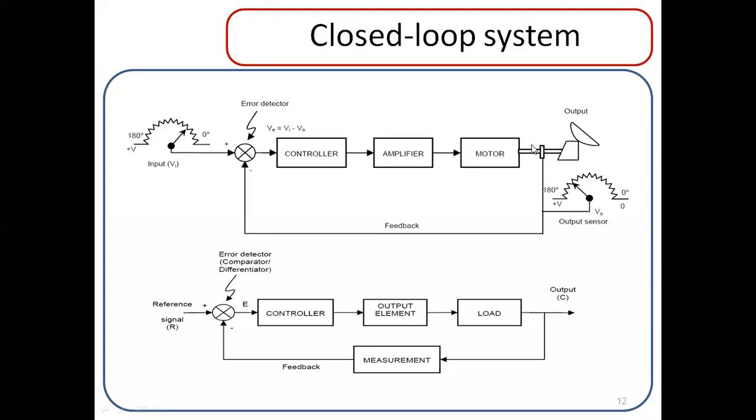Here the inspecting device may be a tachometer. The tachometer will be connected to the motor shaft, and that will give a feedback signal to the error. So the input condition here is that the motor rotation needs to be maintained at 300 rpm.